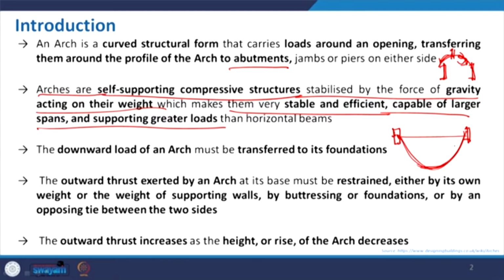We will discuss this catenary form or the parabolic form, and it has flexibility when you add some weight to it. It will change the form a little bit, then you can balance it, and if you reverse this, that will create the arch. So normally it is with a chain or cable, and now converting to the arch form. The geometry we follow to create this arch will determine how it will transfer the load, and this is a very effective form of a structural element that can be used.